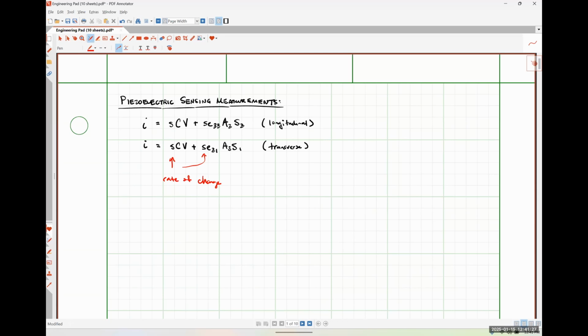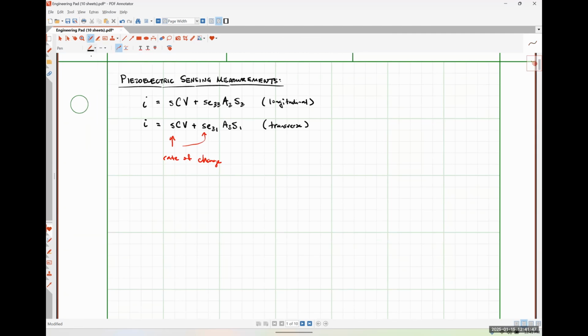So this current is typically extremely small, on the order of picoamperes in size. And so we, typically speaking, need to use amplifiers in our measurement schemes. Okay. So one way that this is carried out, let me put this down here, is a current measurement scheme, through the use of what's called a transimpedance amplifier.